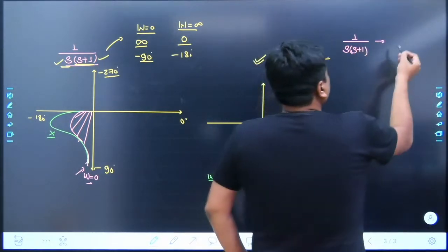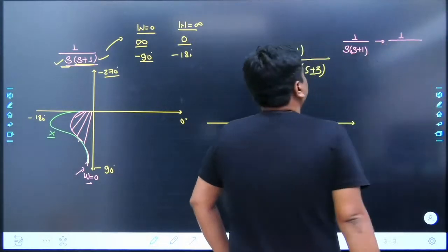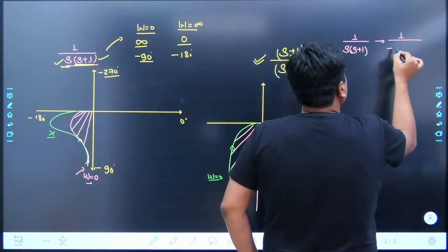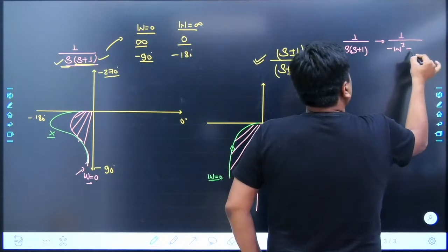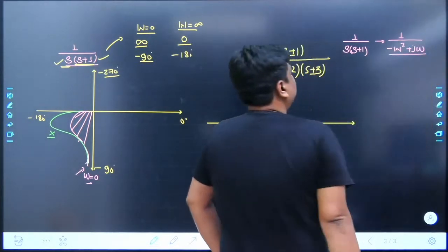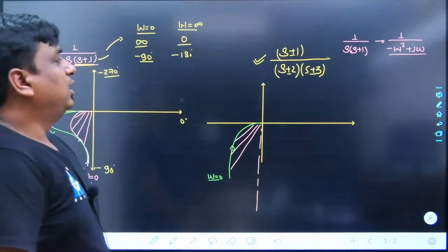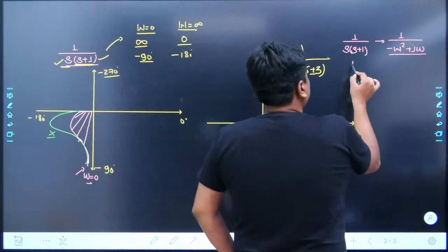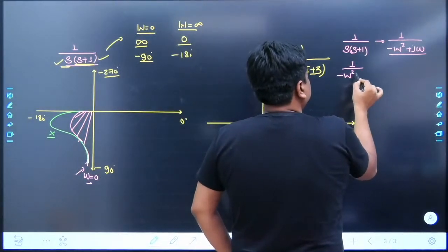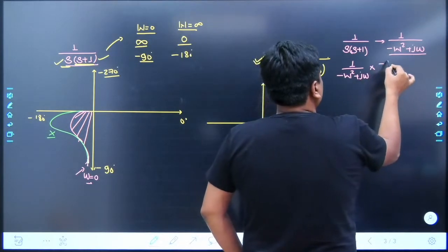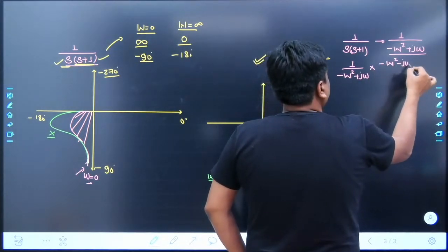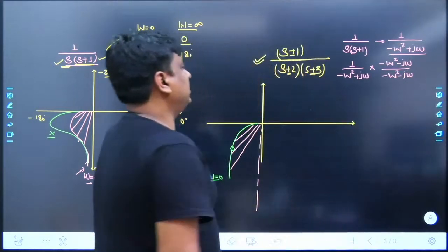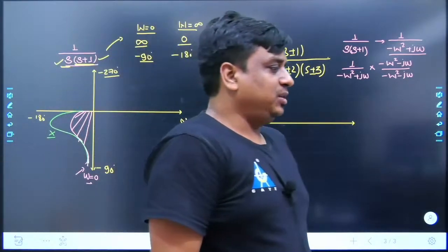Agreeing on it? Let me shift this OLTF into the frequency domain. So j omega multiplied with j omega would become minus omega square, and here it becomes j omega. Yes, minus omega square plus j omega. Let me do its rationalization. The rationalization is being made over here.